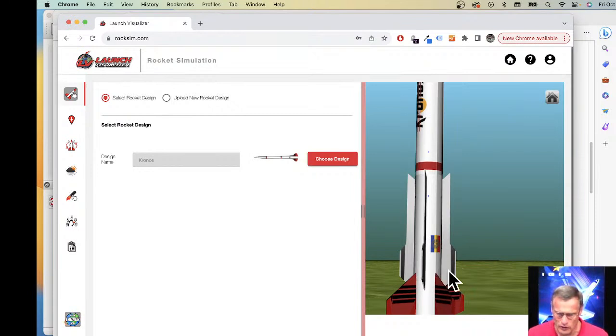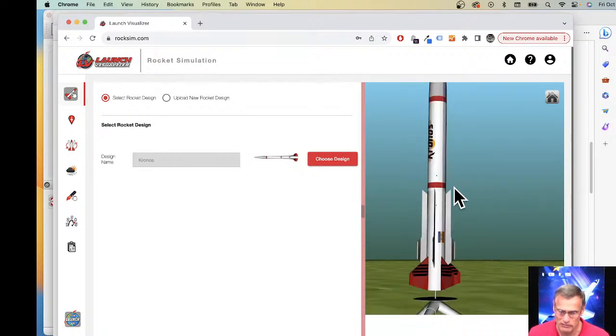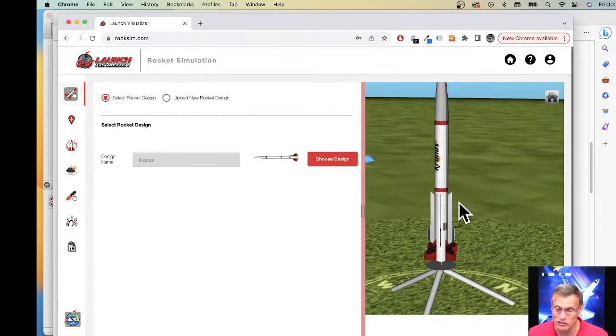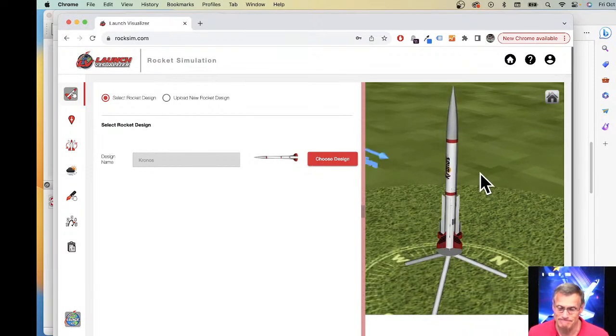And what we've done here is we put these strakes on, and they go all the way up. Like I said, there's a baffle in here, so the baffle actually extends up into this top tube way up here. So we've really stiffened this tube up a lot by putting these strakes on. And that's what makes the rocket strong, but it is pretty light because it's 3 inches in diameter, and we call it a thin wall tube.